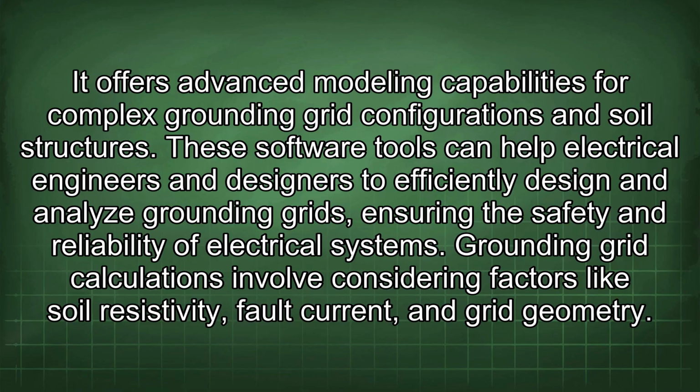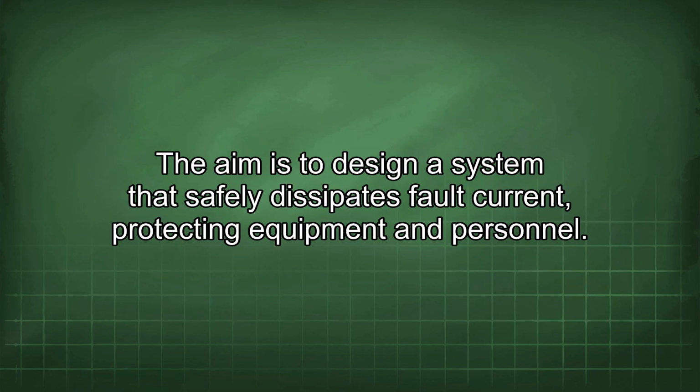These software tools can help electrical engineers and designers to efficiently design and analyze grounding grids, ensuring the safety and reliability of electrical systems. Grounding grid calculations involve considering factors like soil resistivity, fault current, and grid geometry. The aim is to design a system that safely dissipates fault current, protecting equipment and personnel.